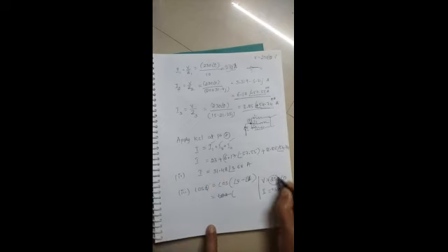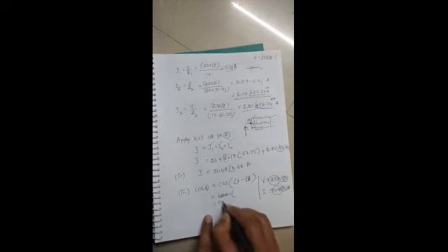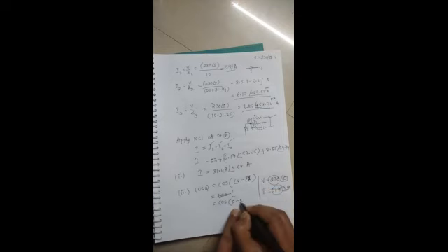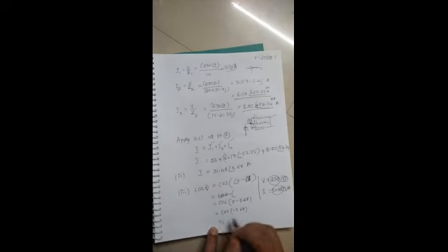This is the magnitude and this is the angle. Take the cos of the angle of voltage, which is 0, minus the angle of current, which is 3.68. Therefore cos of minus 3.68 is your cos phi, which comes to 0.9979. This is your power factor. Now we have calculated the third task also.